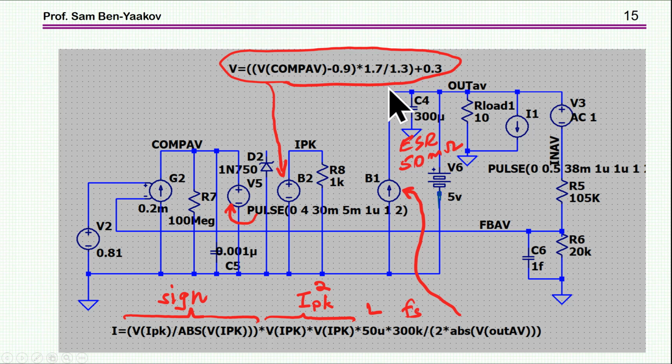It's a linear equation. This is now the voltage coming out of the comparator. This is now the average model, okay? What I have here is the transconductance amplifier. This is the output, and this is the relationship between this output and the actual reference used to compare it to the current. So this is the actual value of the peak current, because the current will reach this value.